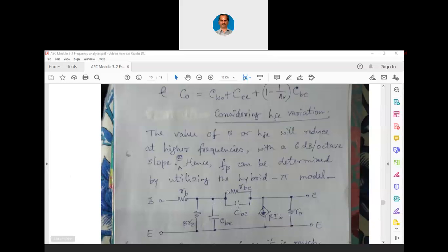But let us add one more thing called RBC. That is the resistance between base and collector. In general, this will be a very high resistance. Because it is a very high resistance, till now we did not add it. We simply ignored it, because when compared to beta RE and R0, that RBC need not be there. But let us add that also now.